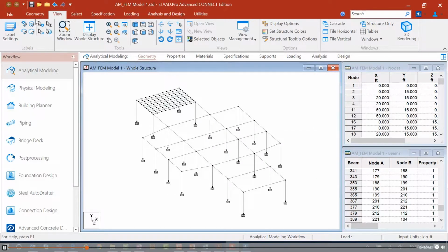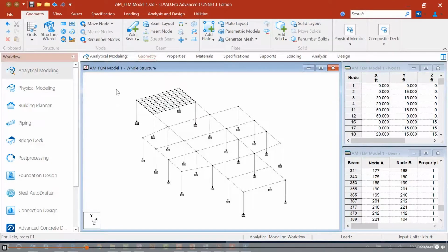Now, in addition to that method, that's a super element method. You're going to create an overall large plate and then break it up into small ones. I do have an option to skip that first step and go straight to a finite element mesh. To do that, you're going to access your Generate Mesh tool. So let's go ahead and click on that tool.